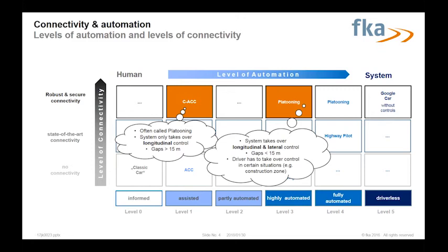And here, what we can see, if we talk platooning, the longitudinal and lateral control is taken over by the system. So the driver does not have to steer. The driver can relax, and the following cars just follow the first truck. And if we have the steering control by the car, we also do not have an issue using these shorter gaps, because the driver is not responsible anymore for the steering. And this is important, and this makes it much more difficult. If we have to control the steering system, and we just have a gap of 10 meters, it is quite difficult to really measure the lane markings, so the control is not really easy, but it's feasible. We have shown this in many projects.